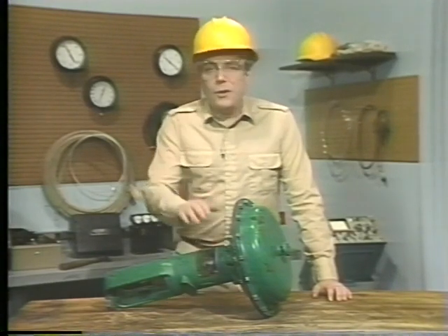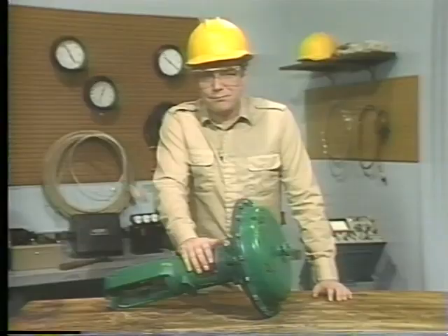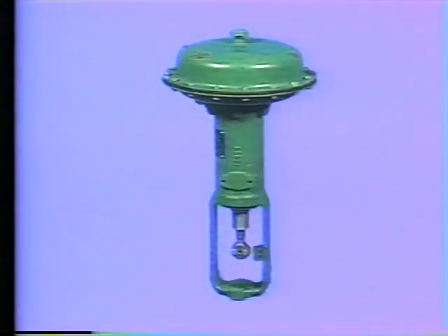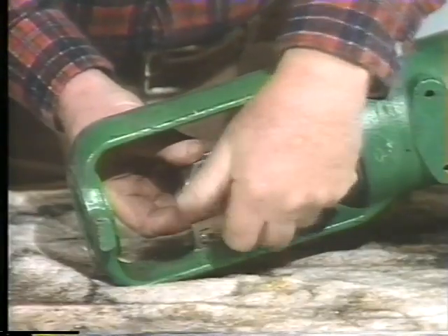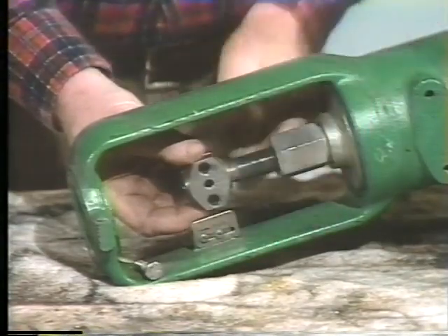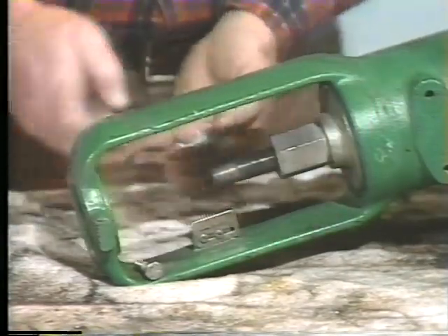We'll start with a pneumatic diaphragm actuator. You may recall that in a diaphragm actuator, air pressure acts on a diaphragm in a pressure-tight case to develop thrust and produce motion, which is transferred by this metal rod to a final control element. In this case, this metal rod, which is called the actuator stem, was connected to the stem of a valve. The valve is not shown here. The actuator stem is coupled to the valve stem by this stem connector.